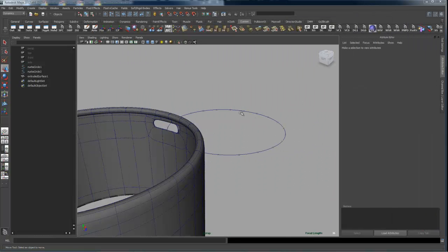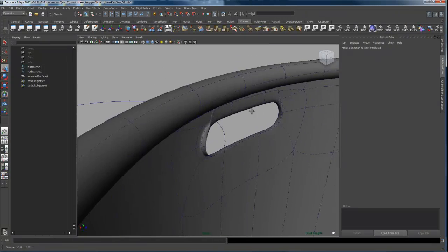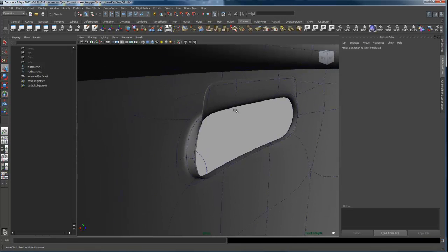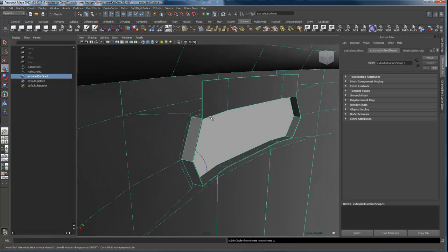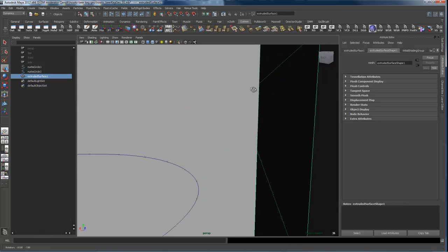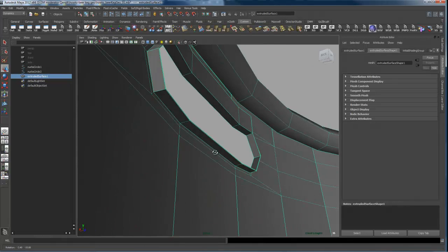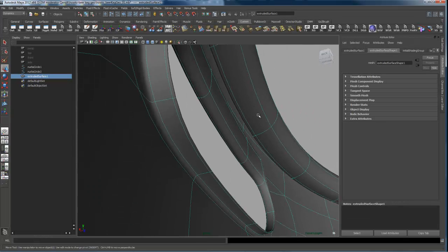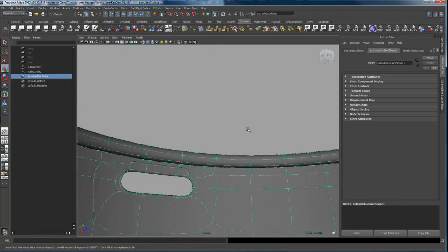Once again, in Maya there are lots of different ways you can do everything, but here's the result of what I've done. You can see the punched handle here, and I'm going to unsmooth it. I've added some thickness to the whole thing, about 1/10 of an inch, and you can see how I've got that rolled up part of the handle here. If I get in real close underneath, you can see that this upper ring part is also curled around. It's not solid. It curls around, and you can see the break in the edge here. So I'll show you how I did that.